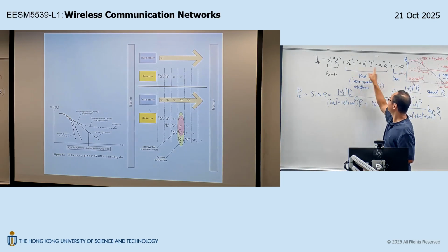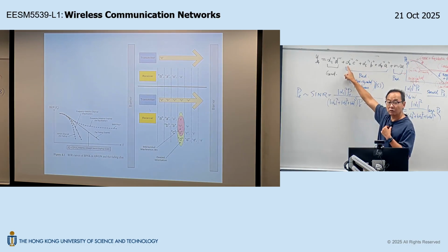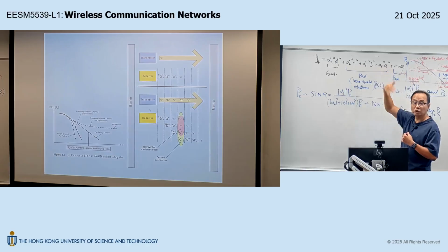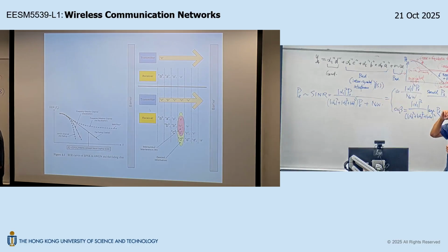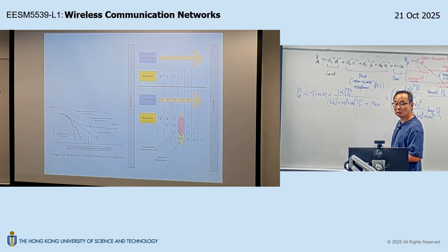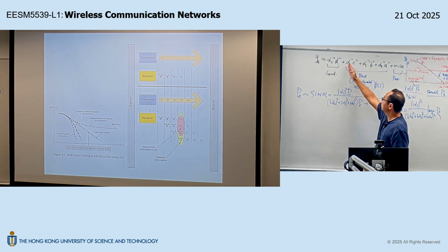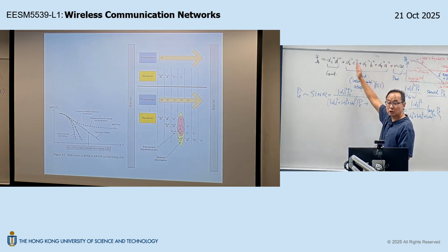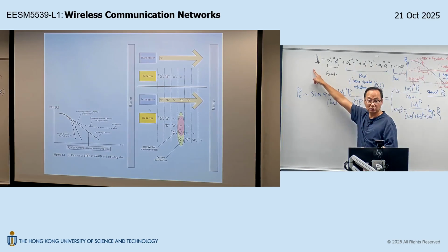So you know B, C, A. You also know the channel fading coefficients, alpha 1, alpha 2, alpha 3, alpha 4, from channel estimation, as we talked about, okay? Then at the fourth time slot, you can regenerate this term. If you can regenerate this interference term, you can subtract it from your observation, right?